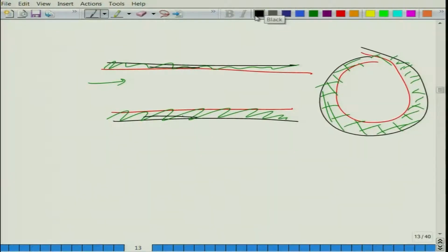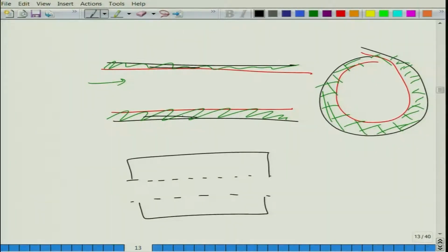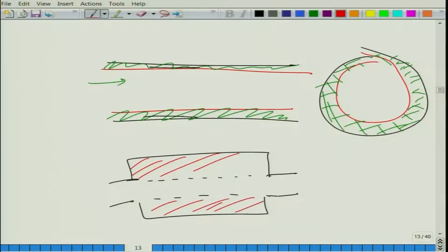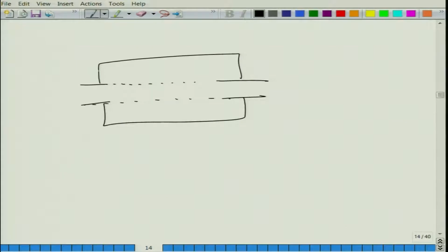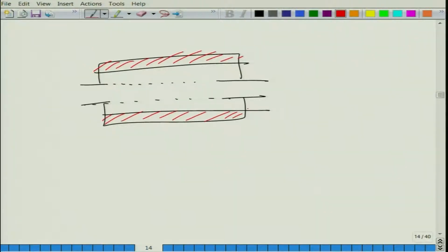This is a simple lined duct, but you can typically have a lined muffler configuration something like this. You have a perforated duct, and the inside of this is filled with rock wool, glass wool, mineral wool, or some kind of acoustic absorbent material. Another kind of dissipative muffler that is usually encountered is this sort of thing, which is really called a hybrid muffler. You do not allow the flow to expand completely freely, like I have been mentioning. You have this kind of configuration.